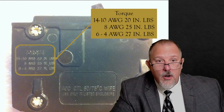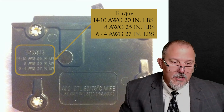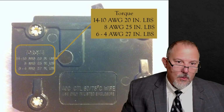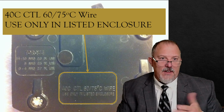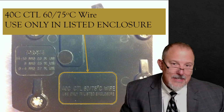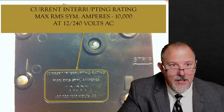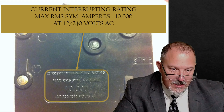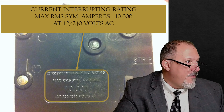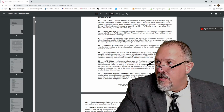Torque. All your circuit breakers are going to have torque published, and this is a thermomagnetic circuit breaker. On the side, it has the torque values. It'll tell you the conductors, 60, 75 degrees C wire use only in listed enclosures, 40 degrees C CTL. And if you want to know the marking, there is a UL marking guide. Yes, there is. And I'll have the link for it down below. Here is the UL marking guide.